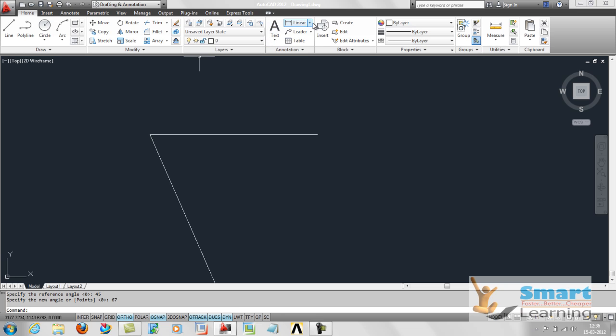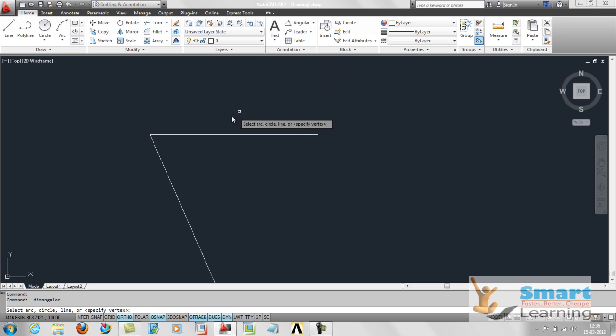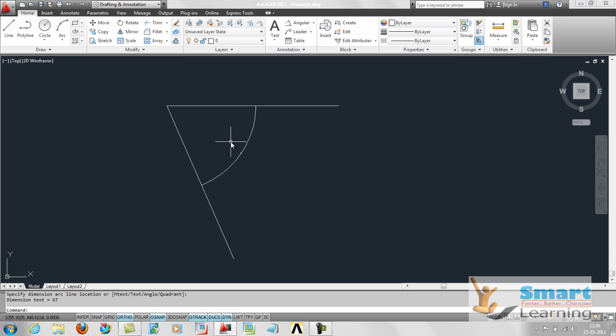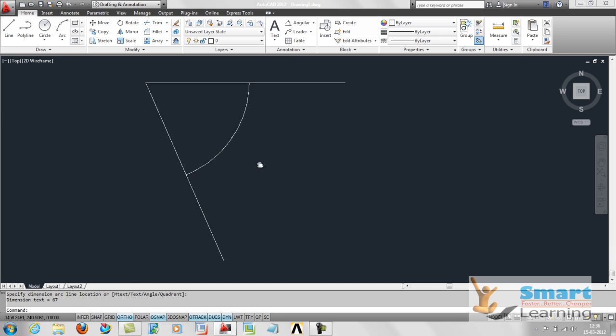This is very interesting and you can do it through your reference object. You can say this is 67, but before we had rotated to 45, so no need to calculate the difference, like 67 minus 45, how much, and then do the rotation. But in the case of reference, this reference dimension can be considered directly and you can do your rotation.